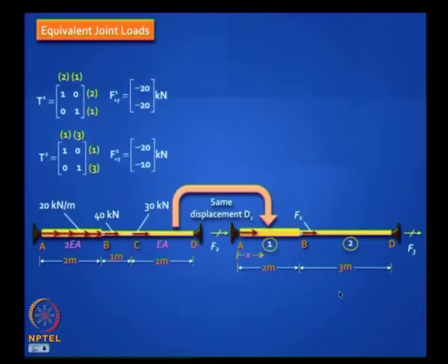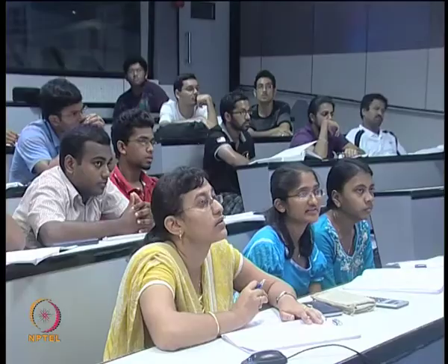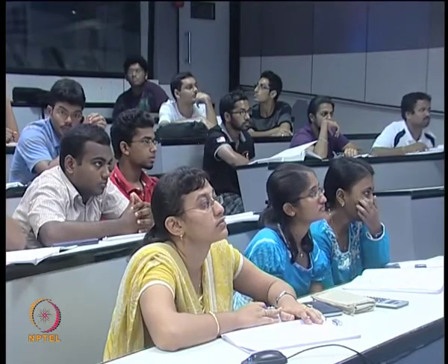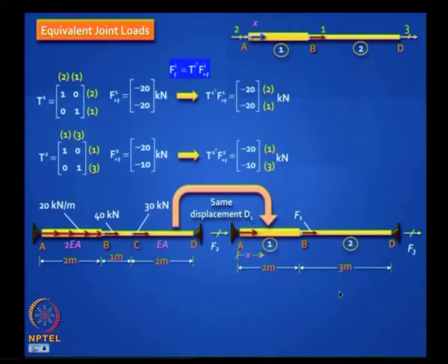So how do you do that? Well, you do it first noting down what you have already done. You have got the two transformation matrices, you have got the fixed end force vectors. What is the transformation you do to get the fixed end forces? You are now moving from local to global. So what is the transformation you need to do? TI transpose, that is all you do. So if you look there, you have to do this. Just pre-multiply by TI transpose, which is no big deal because the transpose of an identity matrix remains an identity matrix. So the only purpose of doing this, you will end up copying the same thing, is now you are bringing in the linking coordinates.